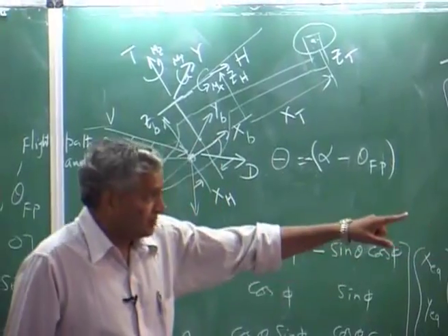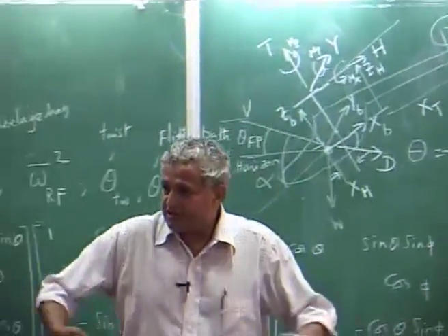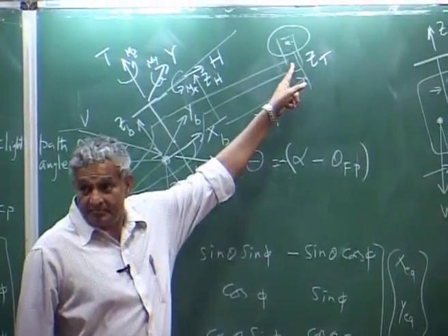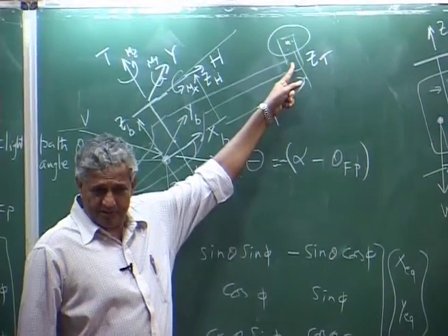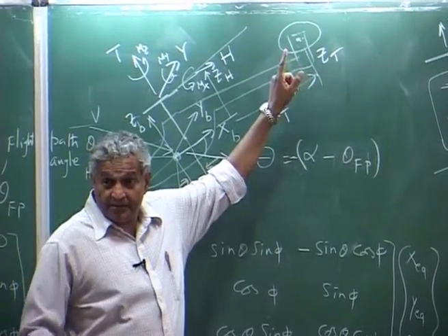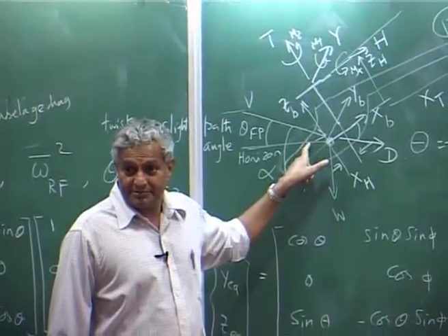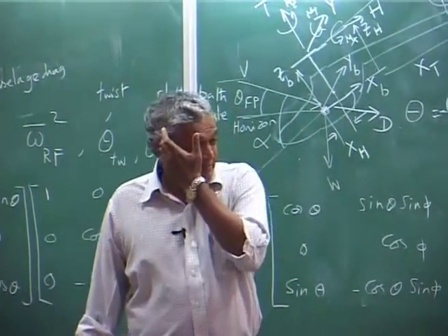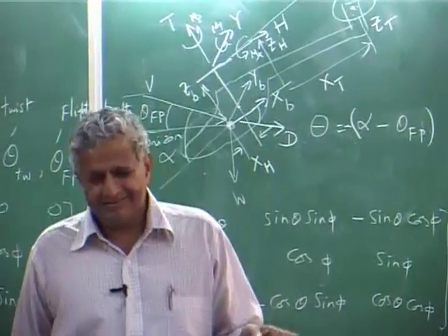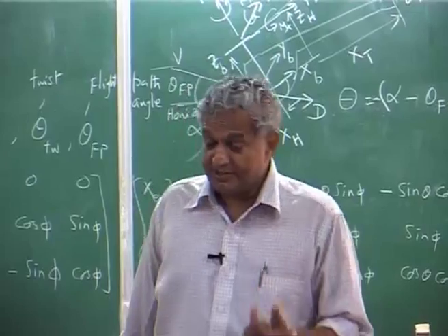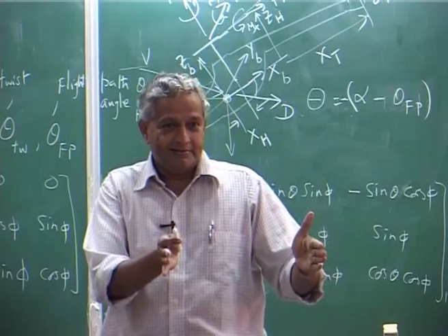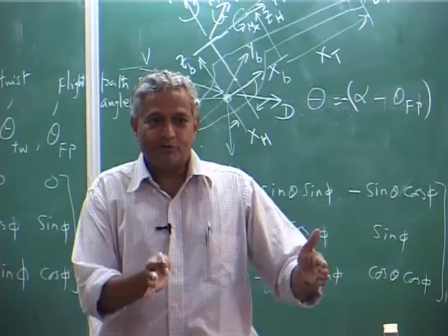Now you see in the pitch moment I do not have any horizontal surface. If I put a horizontal surface here, like a small aerodynamic surface, a flat plate kept at an angle, that will give a pitching moment. So, usually big helicopters they have that. If it is a small weight class, they do not have, but sometimes you will find some helicopters have only one half of the tail, not on both sides.